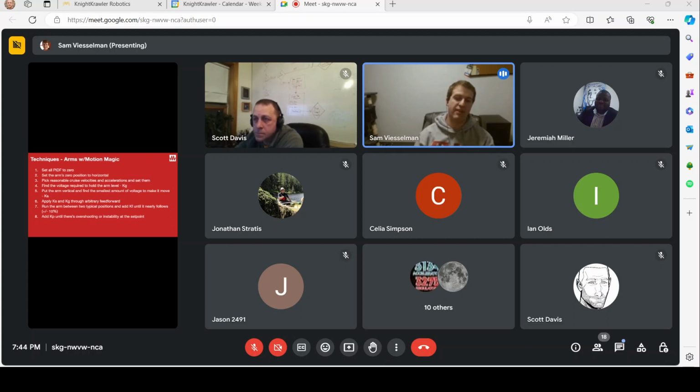Well, that means your cruise velocity, your max speed, is probably going to have to be basically 33 degrees a second. So you need to convert 33 degrees per second into the motor controller units. And I guess that's where some of the numbers get hard, because all the motor controllers are a little different, and it depends on where your numbers come from.